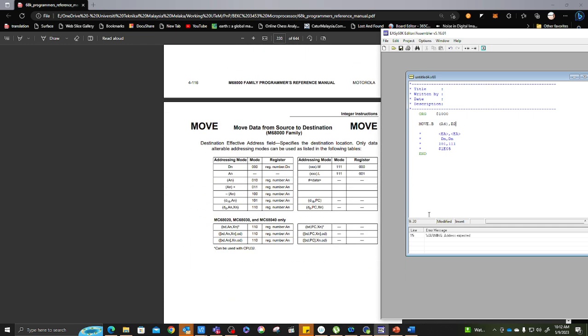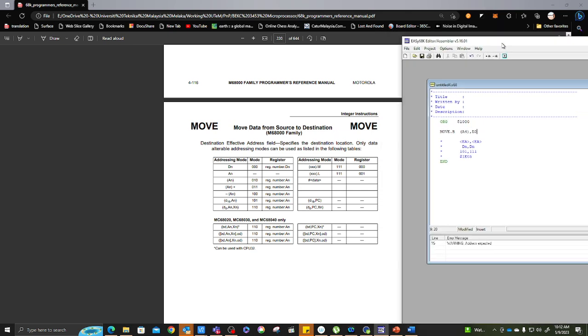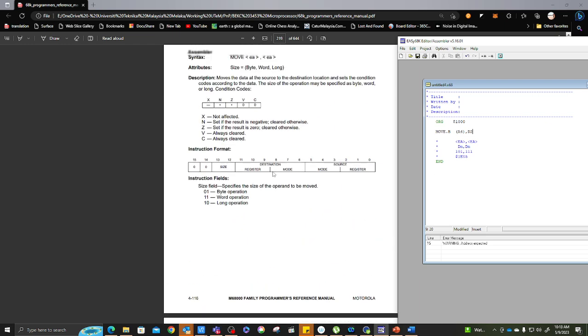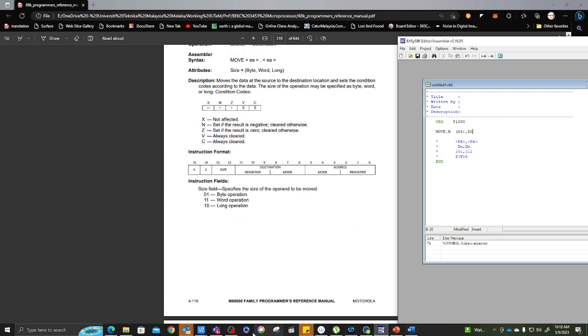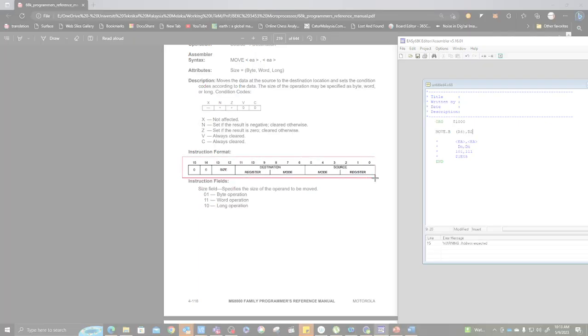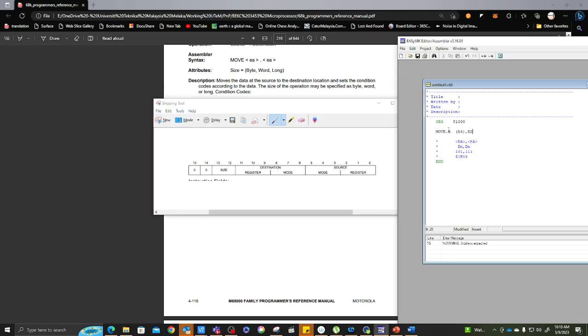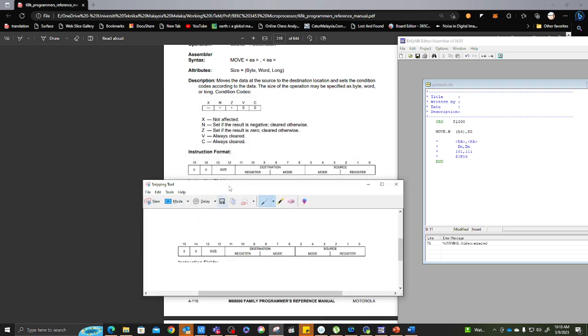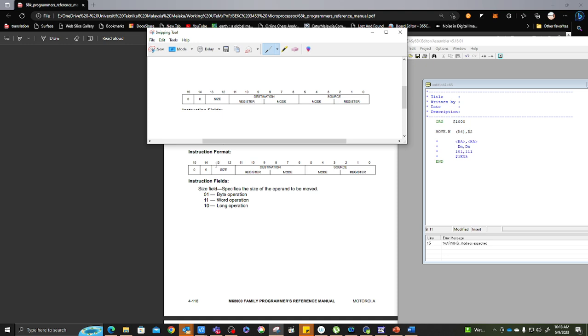Okay, right now the command is changed from data register just now to bracket A4. So it means right now you have to use this one again, the same exact thing again. Let's change it, instead of move.byte, to move.w. Okay, let's look at it one by one. 00 is always there, right? Then you have the size. Size is a word operation. So word operation is 1 1.